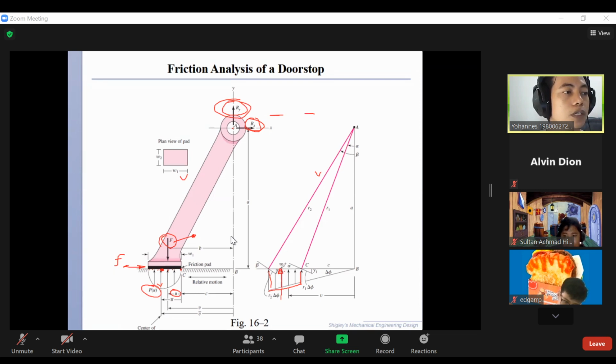Then using this knowledge, using this data, because we have the radius here, we can calculate what is the maximum torque that can be stopped by this friction path. So we have the torque capacity for this brake or clutch. So the maximum power to be transmitted through this clutch or brake is limited by this friction force. And this friction force is a function of the friction path material and also the distribution of pressure. So knowing this allows the engineer to modify the material of friction path to optimize